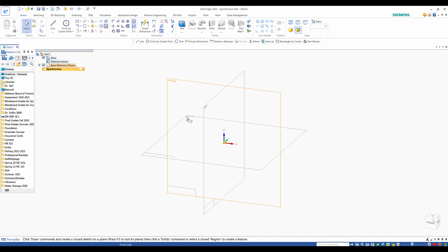I'm going to draw my stuff, say, in the top plane. So I'm going to select the top plane. The best way is to say this is the plane I'm going to start doing my sketches or my drawing. And this is the one which will host most of the sketches or the drawings. So the first good practice is what? To lock yourself to the top plane. How to lock yourself to the top plane?